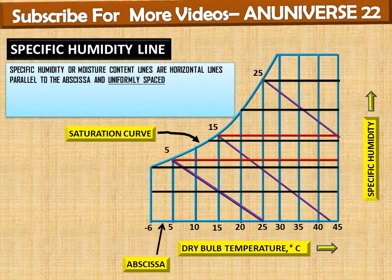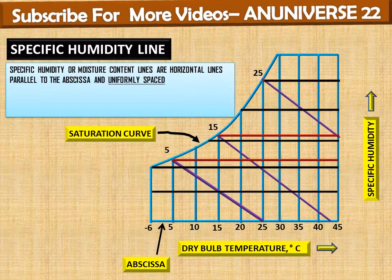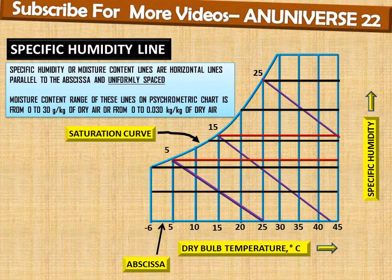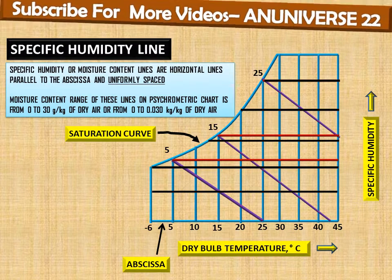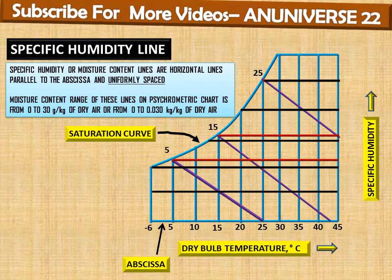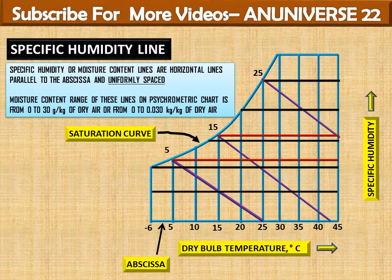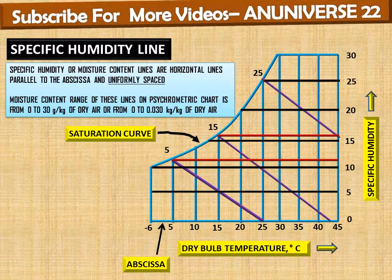So these black lines on the diagram show the specific humidity or moisture content lines, and the moisture content range of these lines on the psychrometric chart is from 0 to 30 gram per kg of dry air, or from 0 to 0.030 kg per kg of dry air. So this is the range of the moisture content. As we can see here, it varies from 0 to 30.